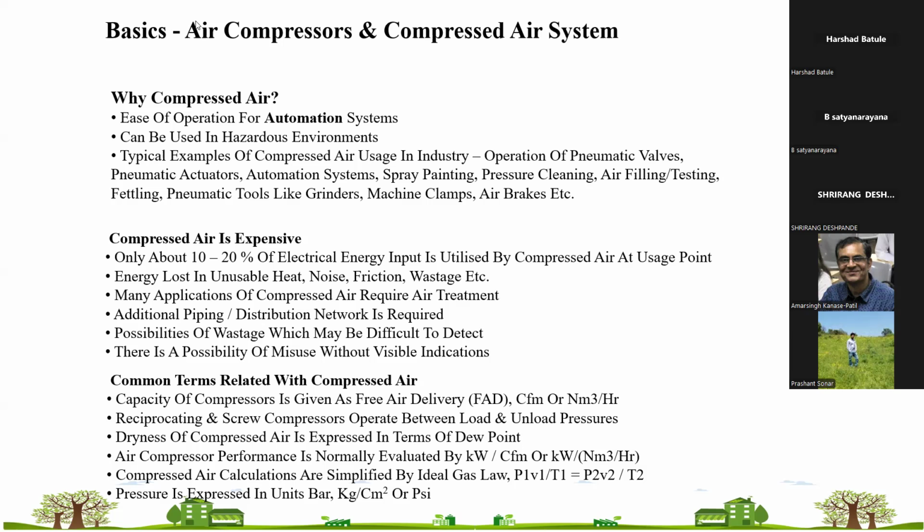That is called free air delivery, the main term of your air compressor. The capacity of a compressor is established in free air delivery in CFM or Nm cube per hour. What is FAD? We'll be reviewing that in the next part.